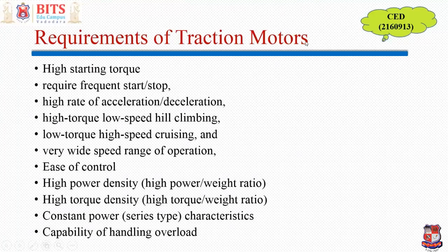It also requires that it should have constant power or series type characteristics. The meaning is that when the speed is 0, it should be able to produce large torque. As the speed increases, the torque is going to reduce, or as the load increases, speed is going to reduce, right? So that is the requirement which we are supposed to fulfill. It should be able to handle slight overload also, because you never know how much the overload will be on it.